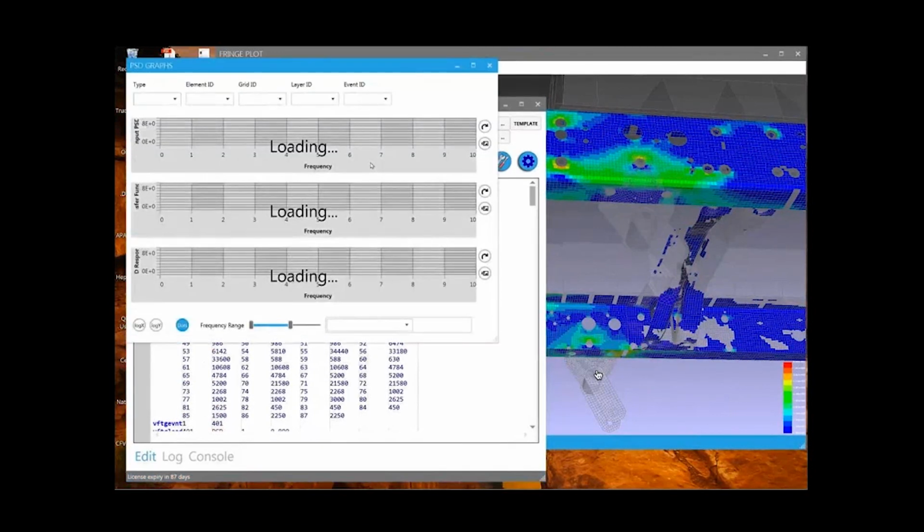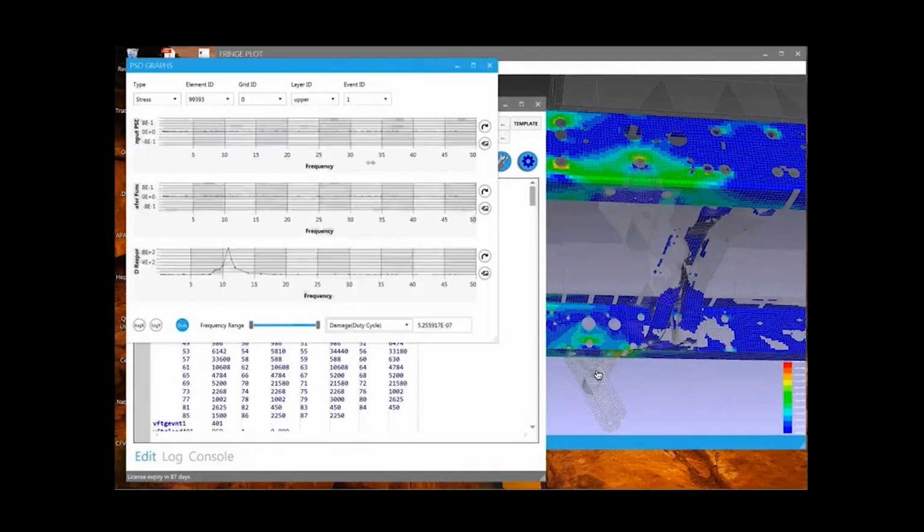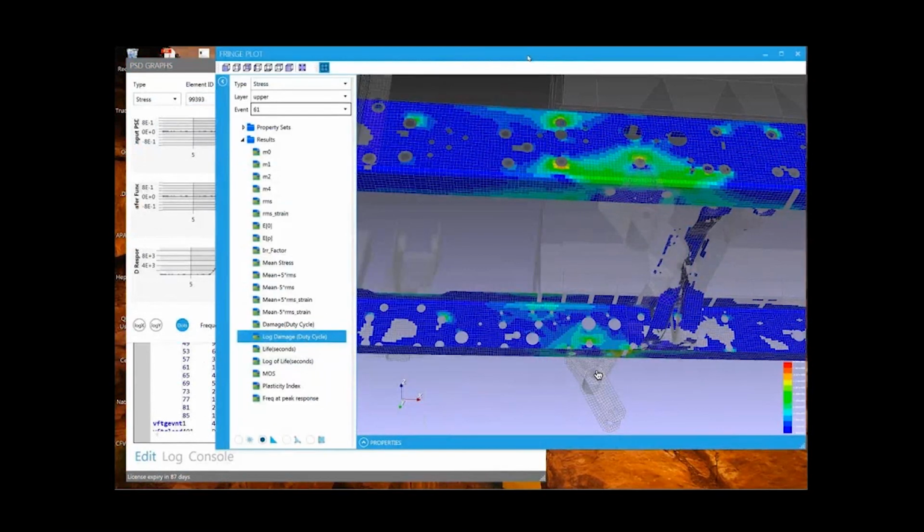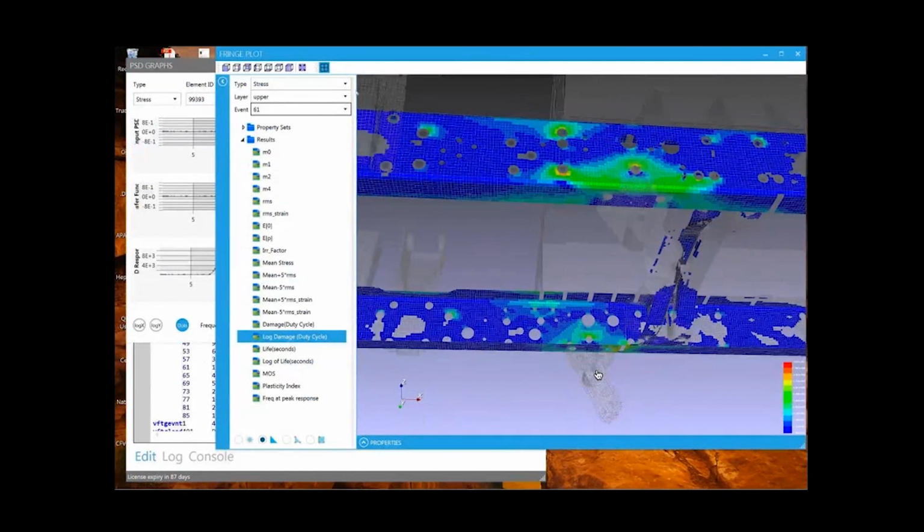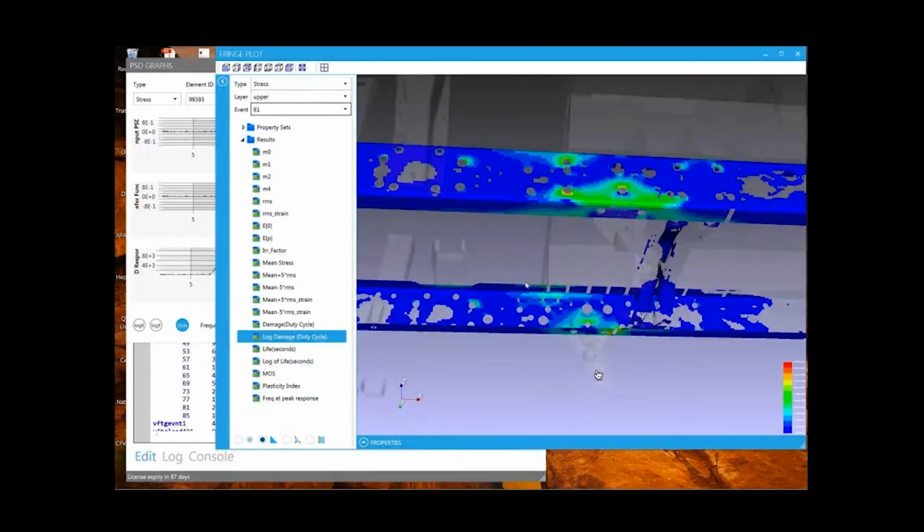Okay, so the event plotter is a very useful way to see the result quantity as a function of event position. We also have another tool for showing the PSD response for a particular event. So if I go to event 61, I can now see what PSD caused that result. And I can do that for any event I want. And I can show with that the result quantity that was created. So this is very powerful results plotting of these capabilities.